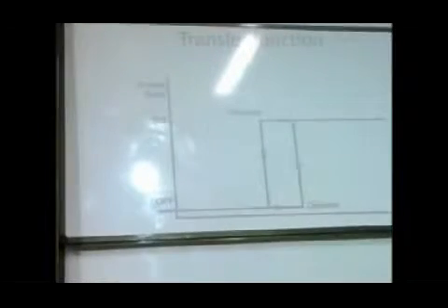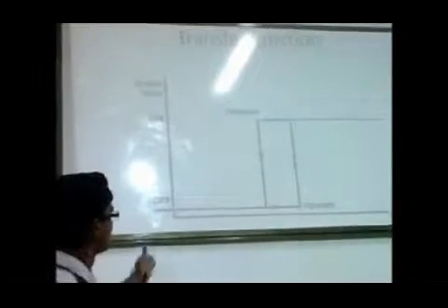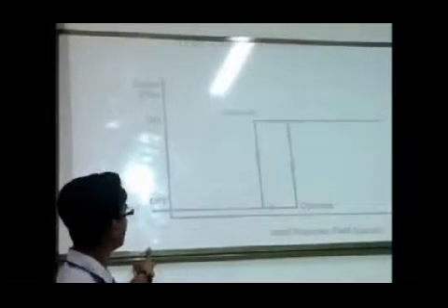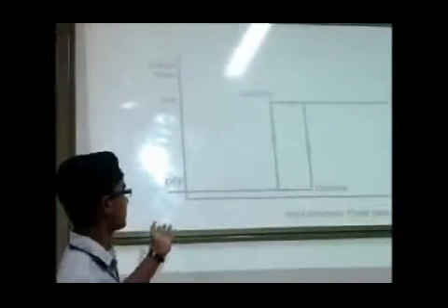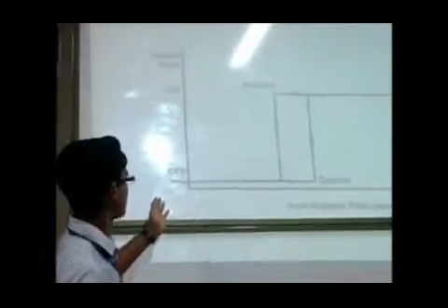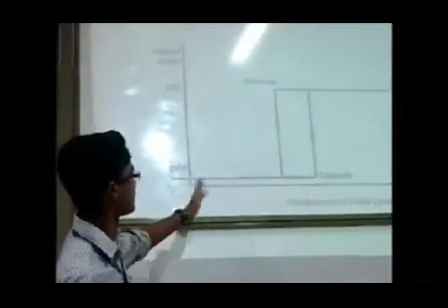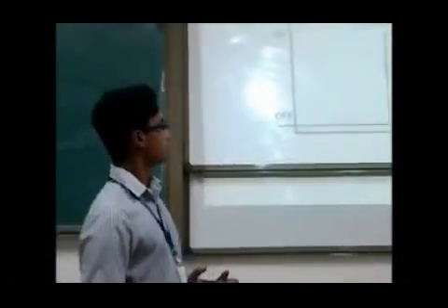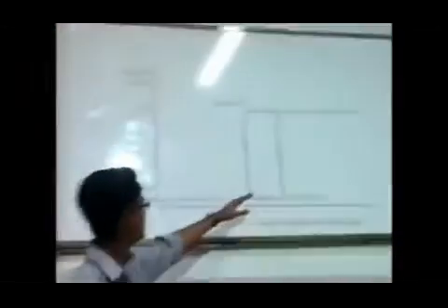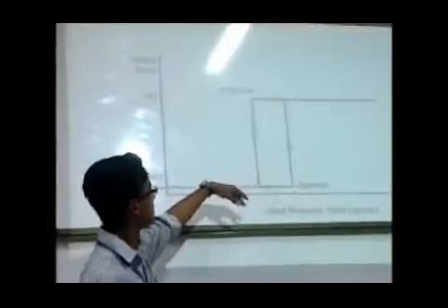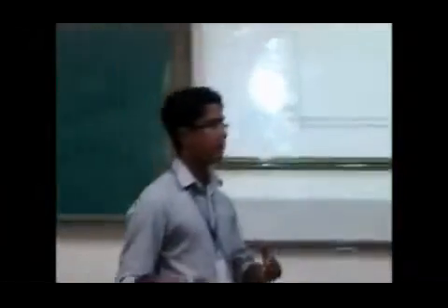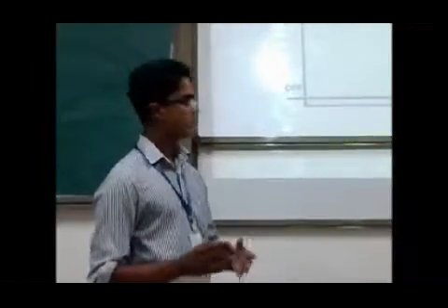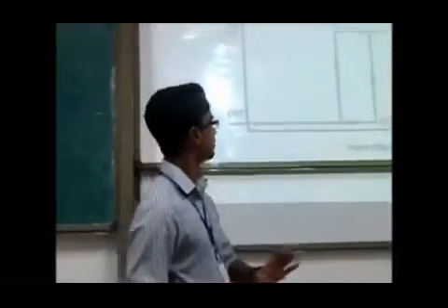Okay, and this is the transfer function. Here we are increasing the magnetic field. Even if we increase it to some extent, the output will remain constant until a point known as the operating point is reached. When the operating point is reached, the output of the sensor will switch from off state to on state, and even if we increase the magnetic field beyond that, it will still remain in that constant stage.